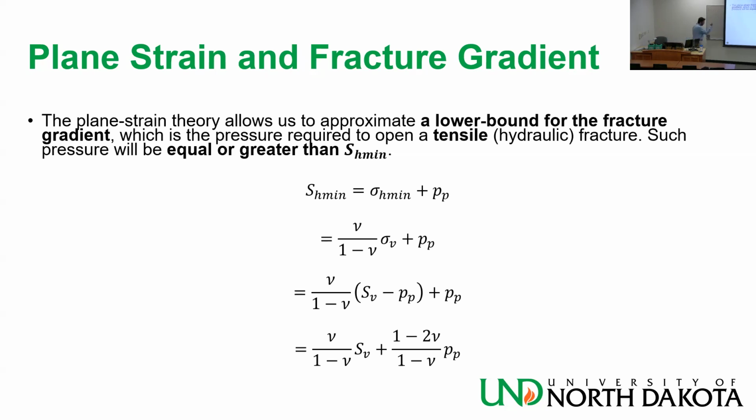And it's very, very easy to drill through those formations, diatomite formations, diatomaceous earth, as we call it. In that case, because it's light, the overburden is small. It doesn't weigh much. So as SV is small, you basically end up with a reverse faulting stress state.